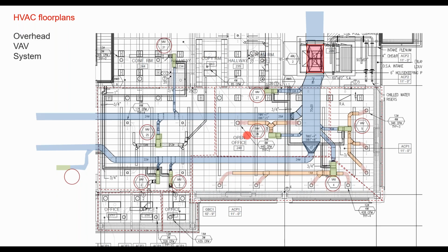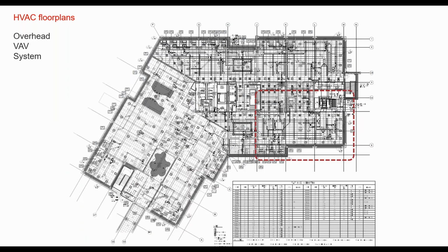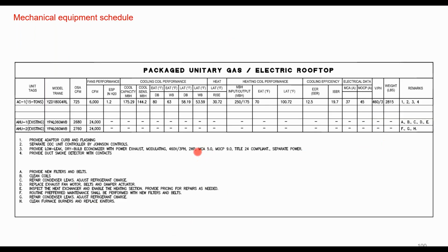Jose noted that the horsepower was on note 3. Yeah, note 3 was only for the power exhaust, right? So that's just CFM and static. The thing is, we only have external static, right? So we don't have total static. So good point. If we had total static, then yes, you could determine fan power from that. But in this case, we only have external. So again, we're still missing a critical piece of information for modeling the fans.